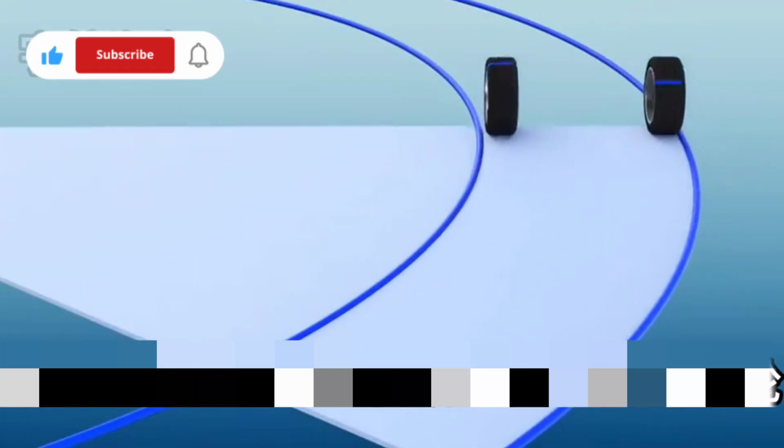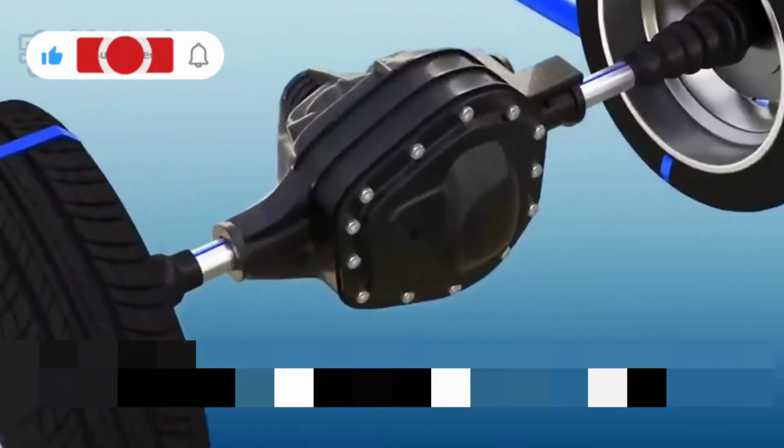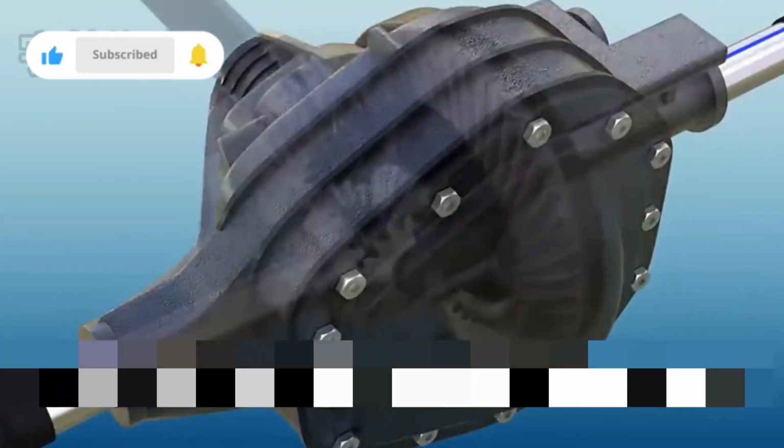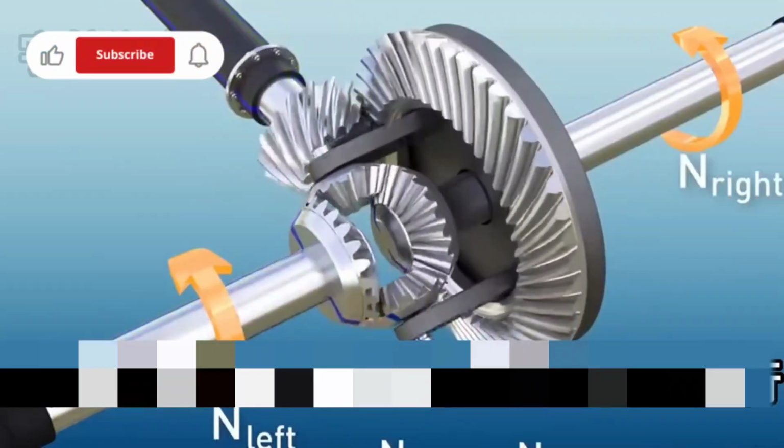When the car is turning, the outer wheel moves significantly more distance than the inner wheel, which means that the outer wheel turns faster than the inner wheel. If the speed is the same, the car will not be able to turn. So the drive axle is not a whole, but is connected to the left and right half axles through the differential. The function of the differential is to allow the 2 wheels to run at different speeds at the same time.